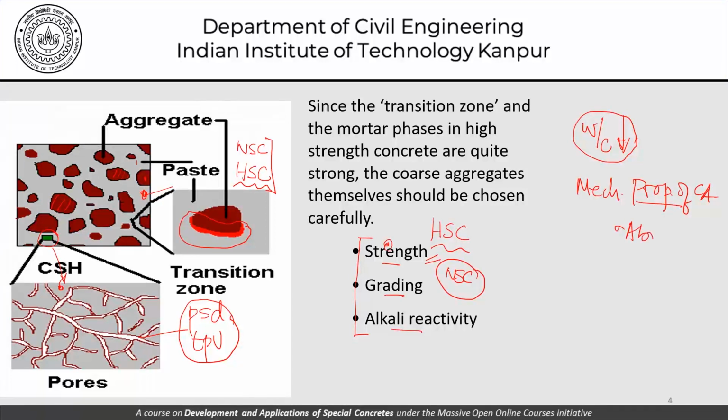We do the abrasion value, we do the crushing value, and we do the impact value. And these three tests essentially represent the strength of aggregates, which is not determined as the strength of concrete is determined by taking a core or by taking a sample and applying compressive stresses to it and causing it to fail. That's one part of the story.